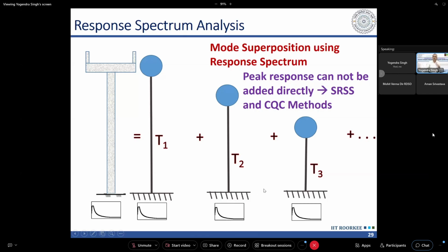Superstructure will vibrate, but the substructure will not vibrate. And as a result, the substructure will remain more or less static, or rather it will be moving rigidly with the ground. That is more appropriate to say. So it will move rigidly with the ground. So you will not get any mass participation from the substructure.